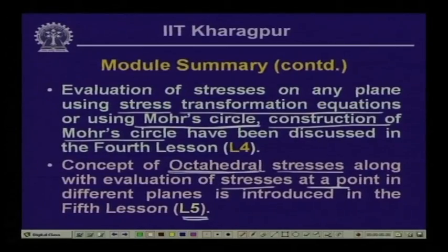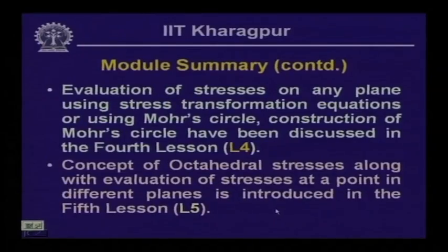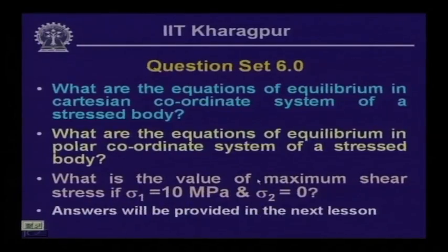As I have told you, the octahedral stresses are the stresses which act on octahedral planes, which are equally inclined with reference to the principal axis system, and these stresses are useful when we talk about the evaluation of stress in the inelastic stage. And in this particular lesson, we gave you the concept of the stresses in a polar coordinate system, which you have already looked into.